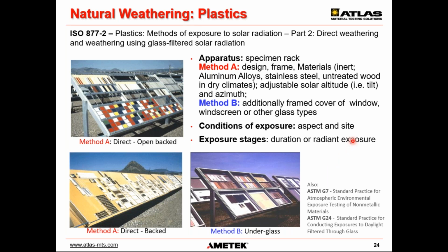Here are some examples of natural outdoor weathering standards showing the popular exposure conditions. I mentioned the open backed exposure, where you have lower temperatures than if you were to use the backed exposures. And here are the underglass exposures for interior applications. Although they're all done outdoors, different applications use different setups.